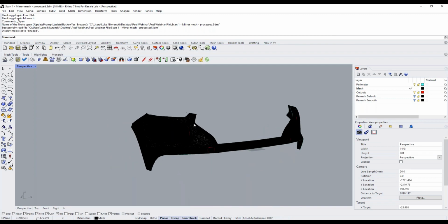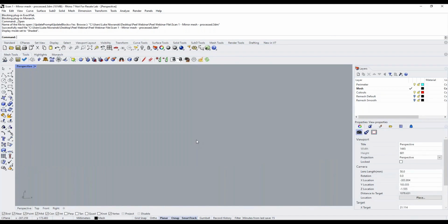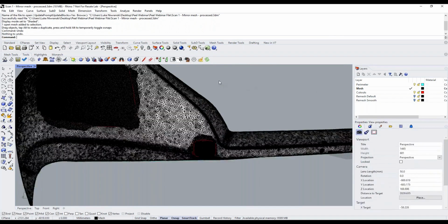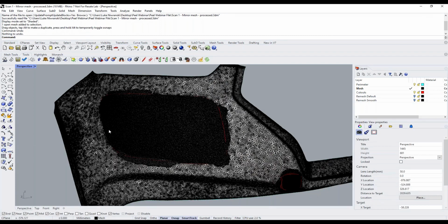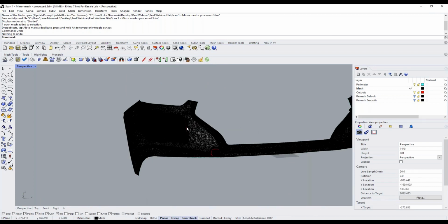I've taken a couple extra steps for this particular model. I've also filled in the headlight and I filled in the holes for where these cutouts were. But I've also created curve representations for where those boundaries were. I want to keep these cutouts or these curve representations because we do want these features to be on our pattern, but we don't want to be flattening those cutouts because they add unnecessary complexity to the flattening process. So instead, what we're going to do is we fill in the holes and then we trace the location of those cutouts on as curves afterwards. This is going to become a little more clear towards the end of the ExactFlat process when we can see the tracing process in operation.